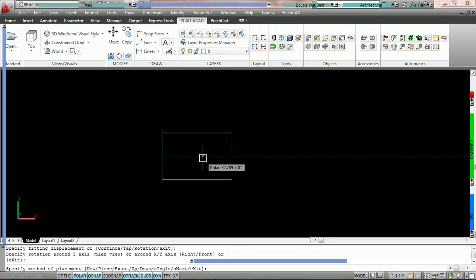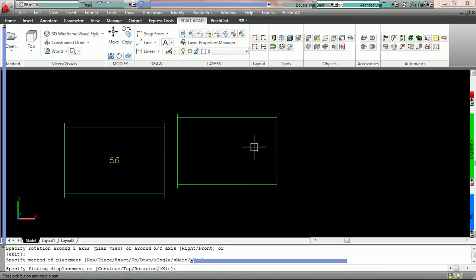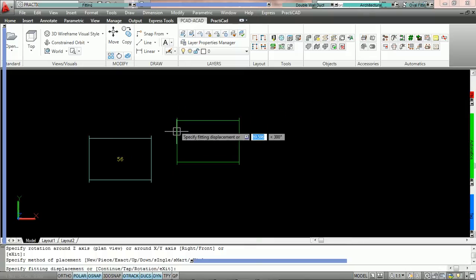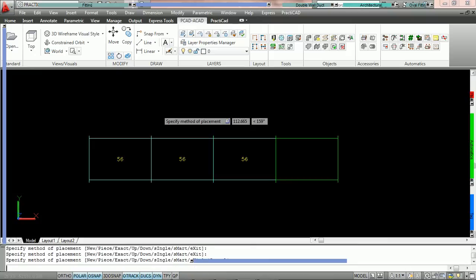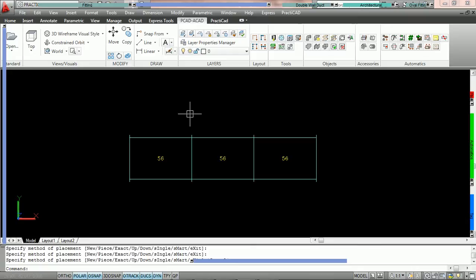And the second we make the last mouse click to place the duct on the drawing, it gets the auto tag with all the placement parameters from that automatic. So every time we add a fitting, we're going to get that auto tag. This is going to make it much quicker to get all of your text on the drawing because every entity you place will have all the proper tags associated with it.